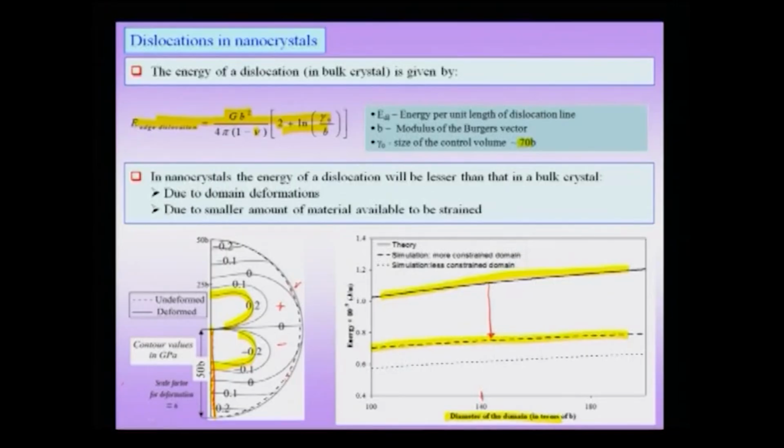Even though this region above is tensile here, if you go farther away, you see that these are regions of compression. That means this region above is now compressive. So though the top-down symmetry is approximately maintained, as in the case of an infinite crystal, you see that the sign switches as you go towards the top free surface, and therefore the behavior is different from that of a bulk or infinite crystal, where the entire half space is purely of one sign of stress.